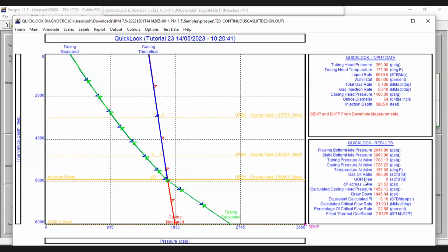So the two possible solutions are the well productivity index and the reservoir pressure. Of course, well productivity index is also related to the reservoir pressure. So reservoir pressure is the one that we are going to change, and based on this, we can have a good match. Of course, in order to have a better match, as a production engineer you need to maintain the model.